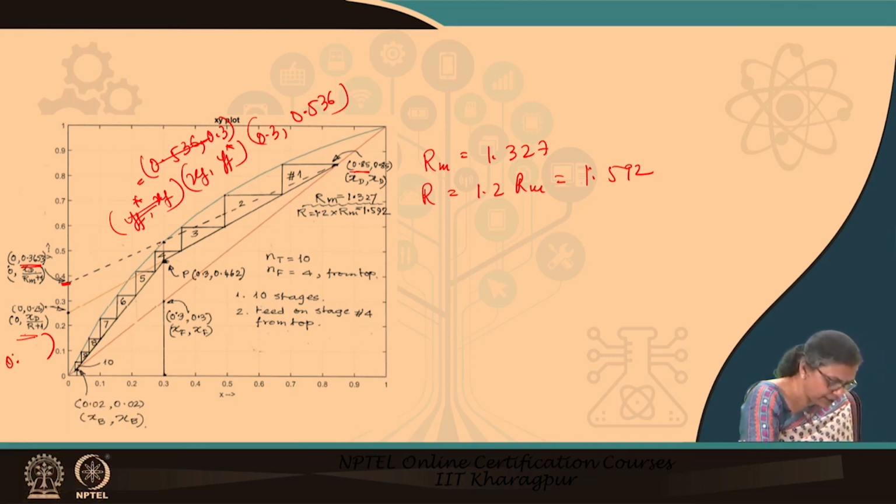Yeah. So, therefore, if you observe this particular point, it is roughly around 0.25. From there we can find out the actual R, which we have already found out, and more or less this line we have drawn. Then from the feed point, since we have taken a saturated feed, we draw the vertical line, and after that we know this point corresponds to the 2% toluene there.